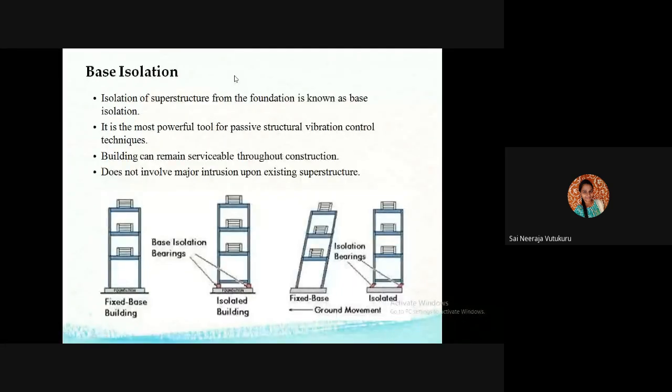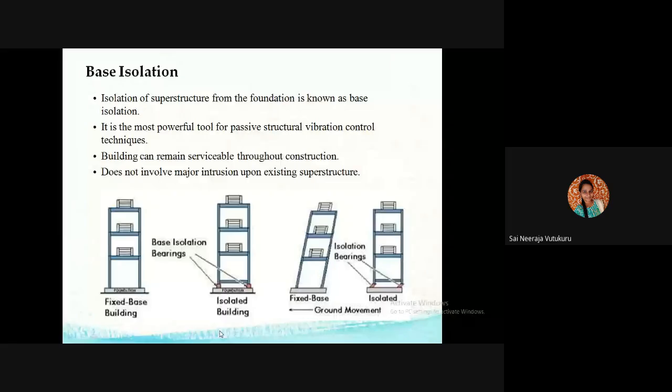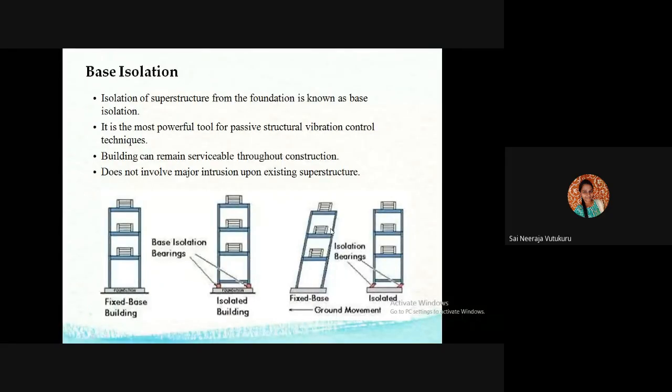Similarly, base isolation. The isolation of the superstructure from the foundations is known as base isolation. Here you can look at the diagram. We have a fixed base at the bottom. This is the isolated building, which means we are placing some bearings in the bottommost portion of the building. Because of these bearings, whatever ground movement we face, for example any kind of seismic load on the building, will not make the building move or shake.